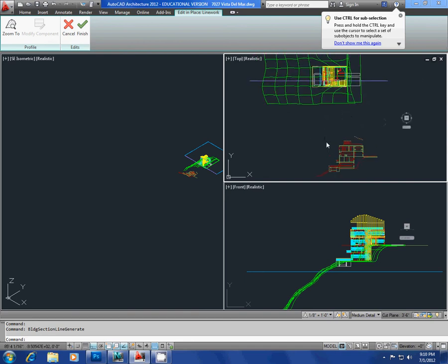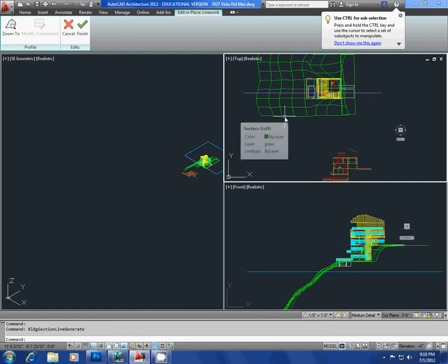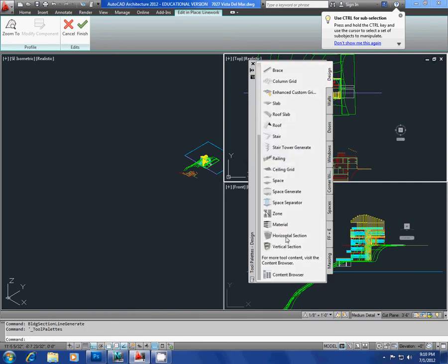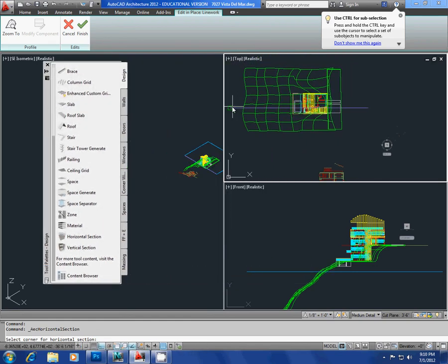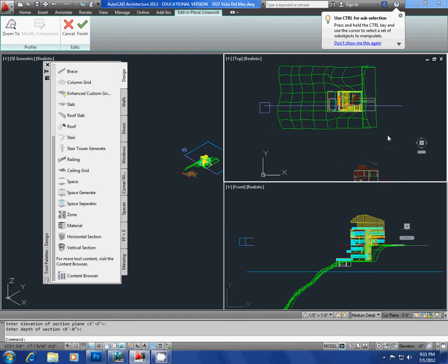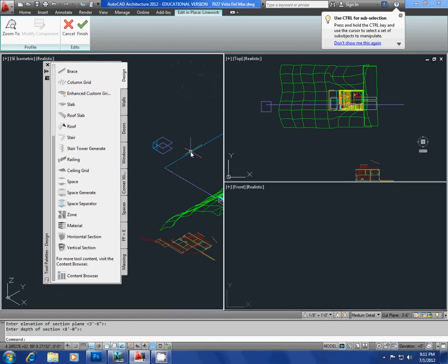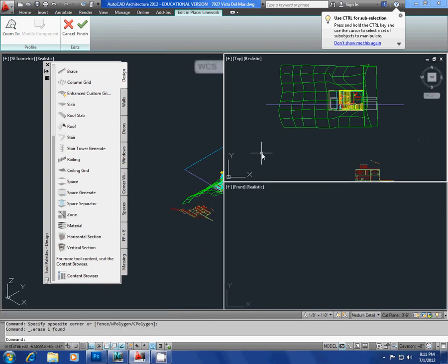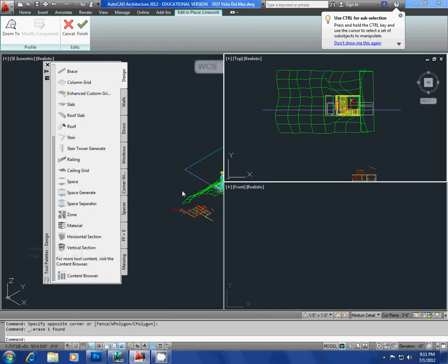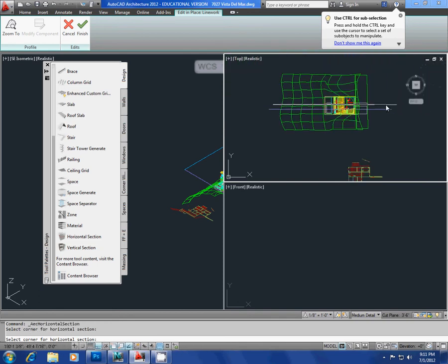And then if you wanted to do an elevation, you would go Control 3, right? You go horizontal cut. Then it asks you, again, same thing. What section to this? Bam. Say go for it. And we would go here. That's a really small box, so I'm going to do it right next to it. Here, to here.